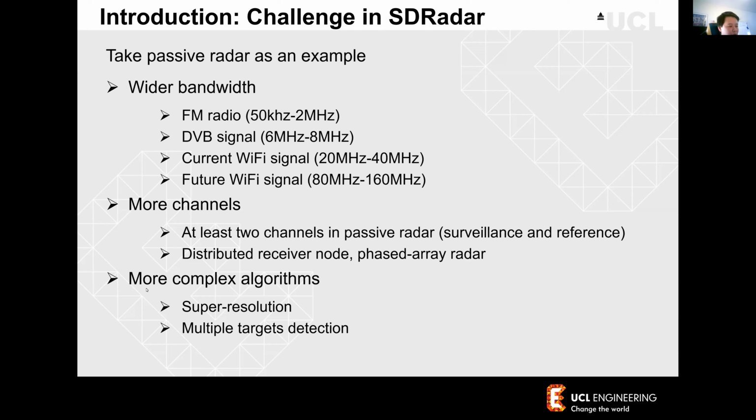Also, we have more complex algorithms. For example, super resolution algorithms like MUSIC and SAGE. These basically search for better resolution than the FFT. And we also have more complex algorithms for multiple targets detection. So basically, you have more targets and more parameter calculation. So this will make the system become more complex. And that's the challenge in the SDRadar.